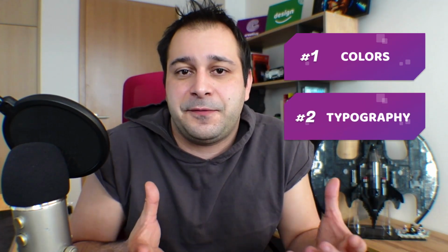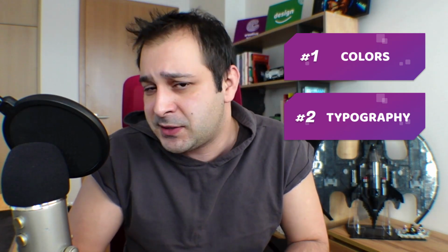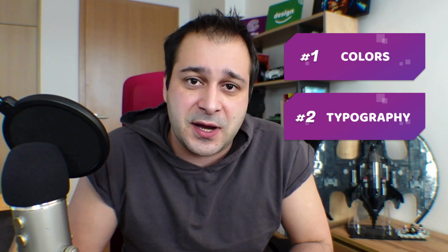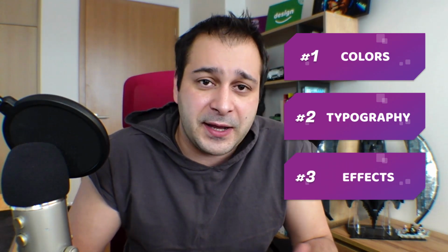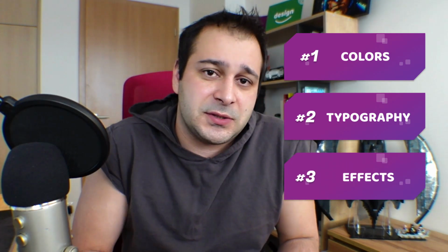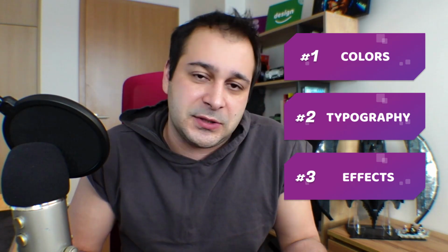I know there are plenty of creators tackling the subject of components and instances and variants. We're gonna talk about those in a later episode. But even before that, keep in mind your components will leverage existing styles. Number one, the colors that you're gonna apply as fill or strokes to different elements. Number two, the typography and basically the font family, the font weight and size that you're gonna use again across your designs. And number three, effects, in case you work with those. And by effects, think of the drop shadows, inner shadows.